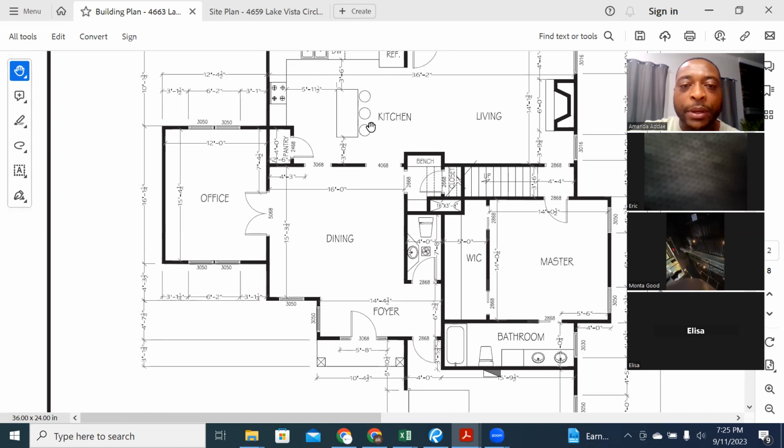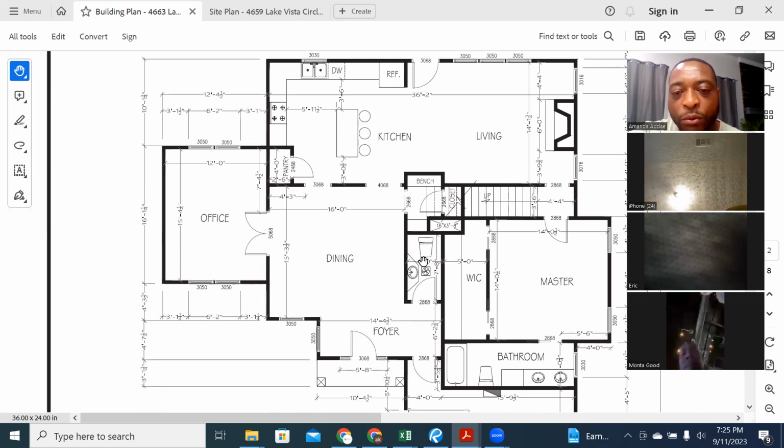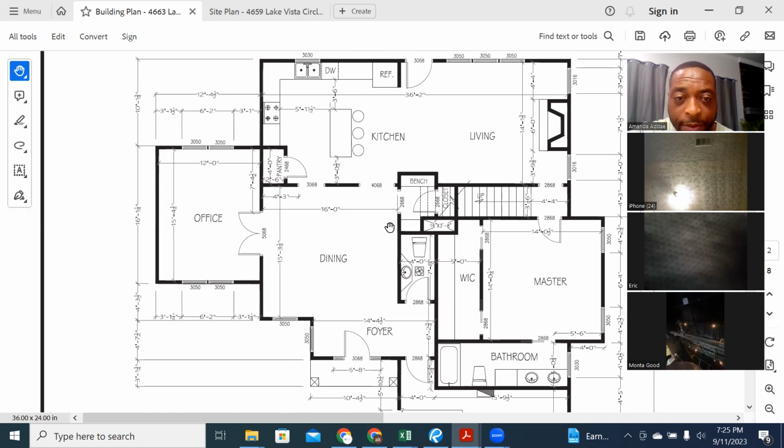So the plumbers are going to come in after our footings are dug, and they're going to run their plumbing, all the drains for all these sinks, bathrooms, toilets, all that stuff. So you're going to see the plumbing pipes in there. And I have that in the video. Okay. So beyond that, after that's done, we're going to get a plumbing inspection. It's a plumbing slab inspection. Those are the phases. So after we pass the plumbing slab inspection, now we can do the slab.